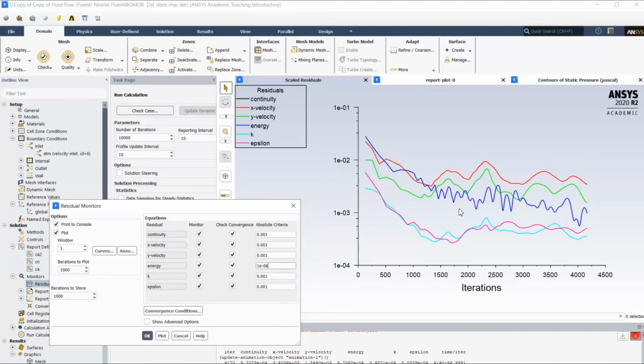But every case is different. We need to see what is the source, where this kind of oscillation happened. It can be seen by analyzing pictures from two different time steps, so you can get the residuals distribution in space and see where it is generated.